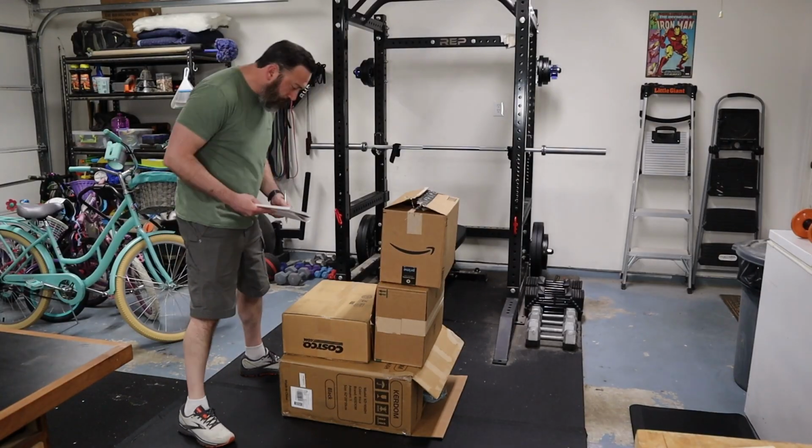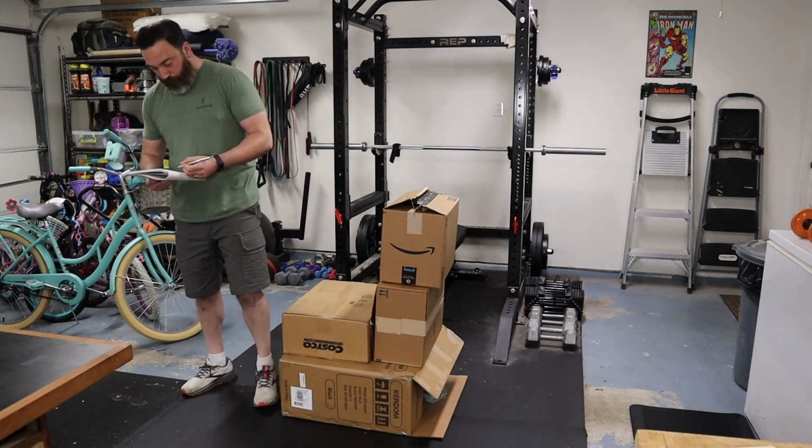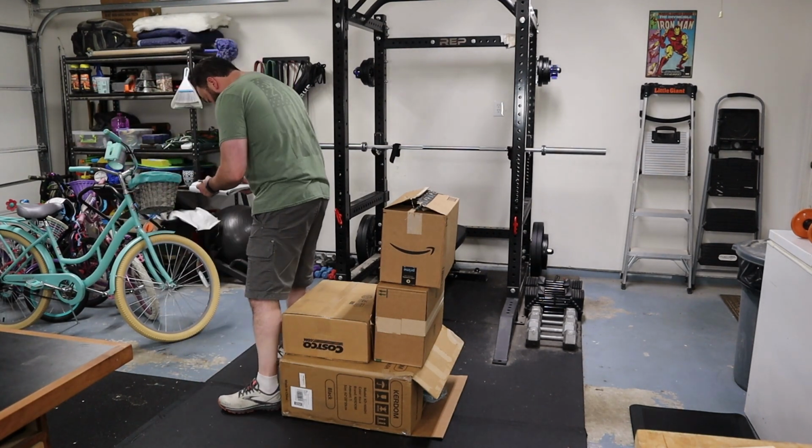Now if it's something that you've never built before and it's completely new, you're not sure if the design is going to work, you can always do some type of mock-up or prototype to test it out. You can do this with cheaper lumber or plywood or even just cardboard boxes. This way you can test out the design and see it in a 3D space before you commit your good materials. Just don't forget, when you're using these cheaper materials, they may not be quite as structurally sound as using the real thing.